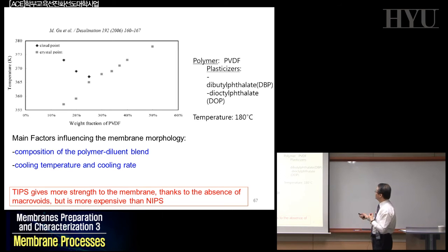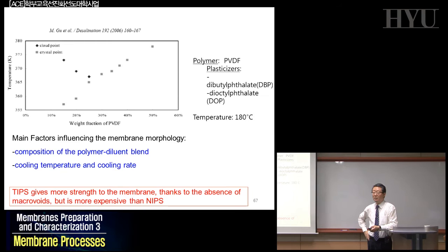Okay? Here in this case, we have DBP or DOP, dibutyl phthalate or dioctyl phthalate, which has been widely used to soften your PVC, polyvinyl chloride. Polyvinyl chloride is a very useful component, but it's a very rigid material because of the dipole-dipole interaction between the chlorine and chlorine in the side chain of your vinyl polymers.